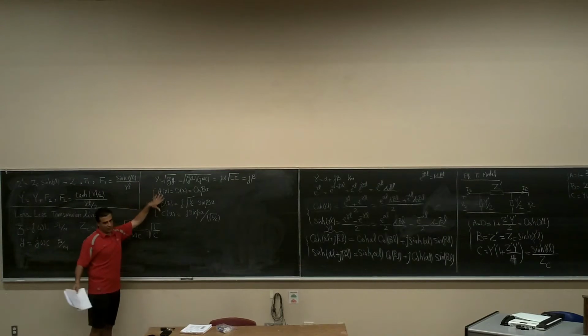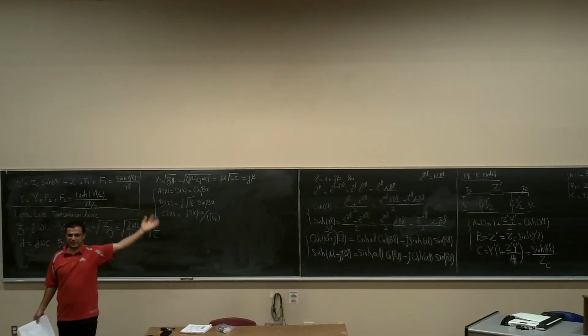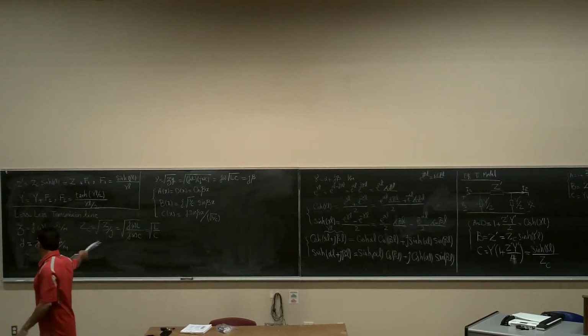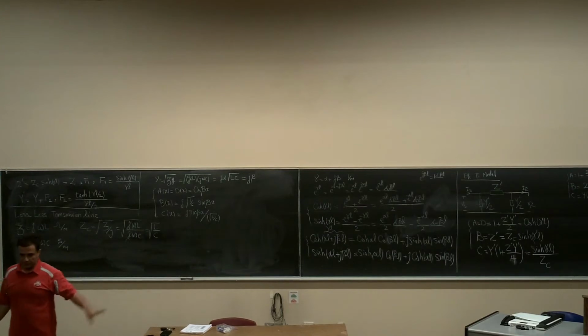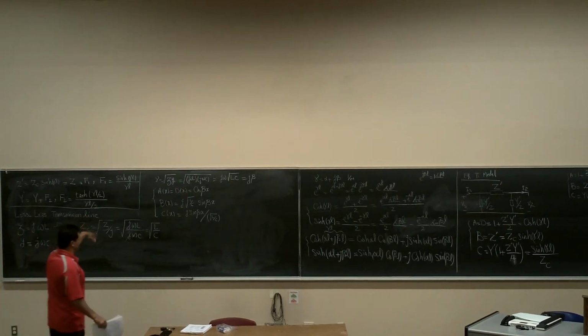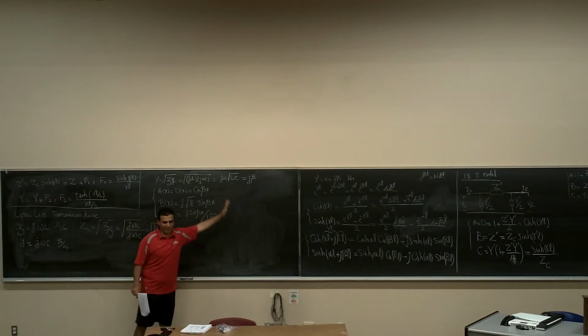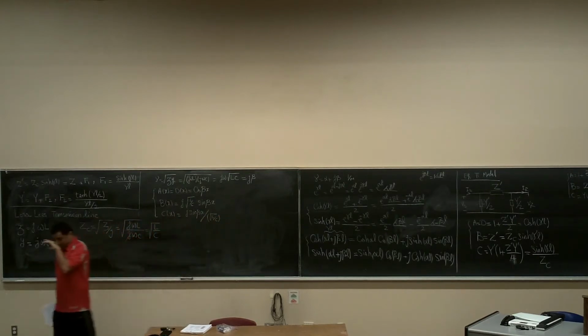So for a lossless transmission line, you just replace this in; I'm saying, just put alpha L equal to 0. Just put the ZC, this value, the square root of L over C. If you replace those two values in the long transmission line model, you are going to get the Ax, Bx, and Cx like this. These are the ABCD for the lossless transmission line. As I said, the calculation is much less than the full transmission line.